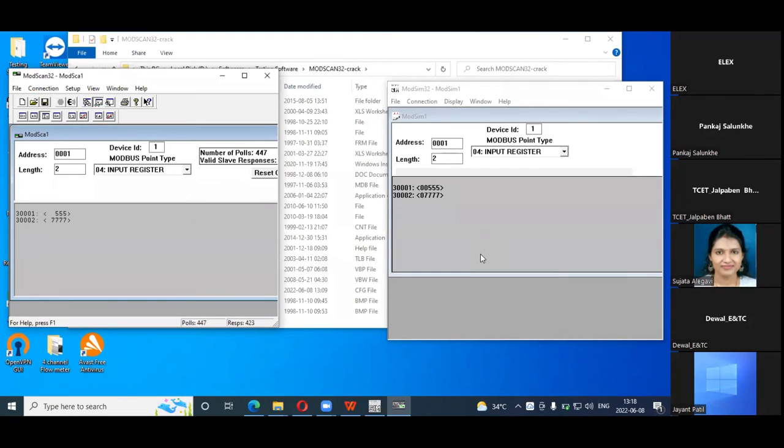Take the example of your RTD or PT100. So all of you know that RTD is nothing but a resistive temperature detector. According to the change in temperature, its resistance increases or decreases. But we can't read that change in resistance directly. So how does that automation or how do your sensing devices know whether the temperature is this one or that one? So according to that, the manufacturers give one table. What is the range of that RTD?